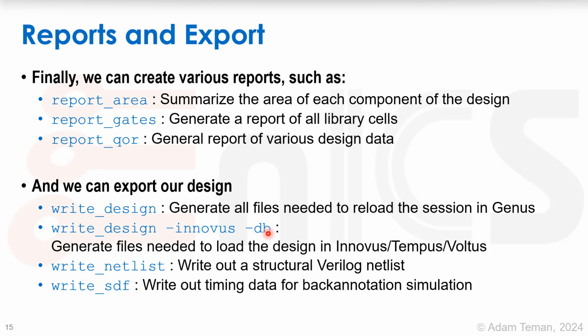If I add the minus Innovus minus DB flags, it will enable us to load the design in Innovus, Tempus, Voltus. That has to load Innovus, so you need the license for it. It also takes a bit longer to do. Okay, write netlist will write out a structural Verilog netlist. Write SDF will write out the timing data for back annotation simulation.